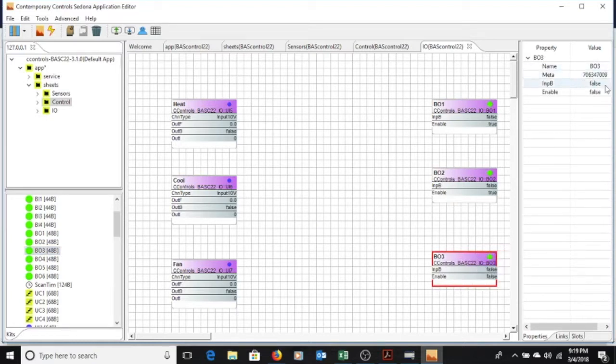Now, your controller, some people might think, okay, well, we only have 6 outputs. Well, if you want more binary outputs, there are 4 analog outputs. If you set the voltages to 10, any 3 to 30 solid state relay will take 3 volts, and you can switch with just relays in between all of these.